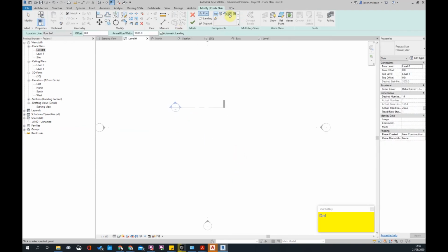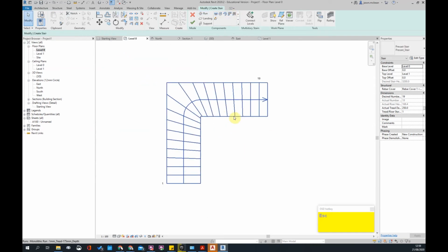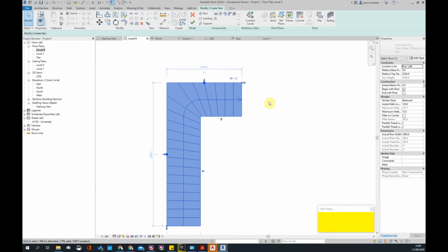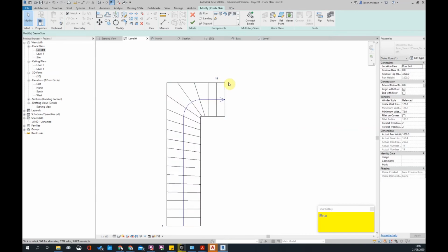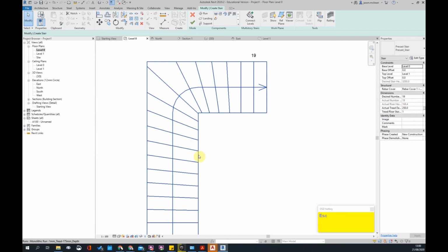Okay, these stairs, generally we don't use these in South Africa that much. They come in preset. You've just got to adjust the side of the stair. And you can change the run location on the fly, center, so that's totally up to you. Okay, so here I've got +2, I don't want that, I only want +1, get rid of one more, there we go. So here we're grabbing, you grab this point and it takes from the, this is also preset. You won't be able to get too close because there's a rule how these are developed.